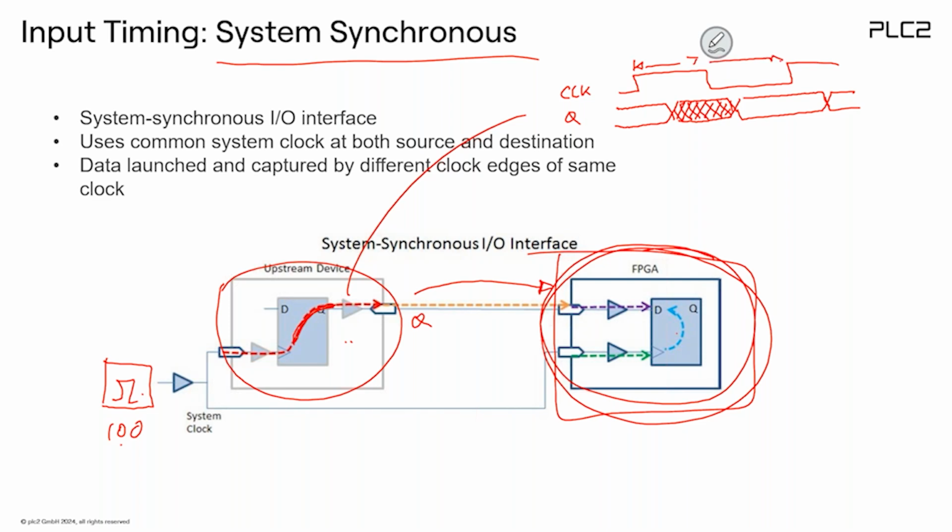Let's say this is from a vendor like Texas Instruments, some component, some chip. In the data sheet you see this information: after the rising edge, for the time T1 min, the data are still the old data. Then after T1 min, the new data appears, and it is stable after the time T1 max. This could be, I don't know, 2 nanoseconds, and this could be 4 nanoseconds. You get this information from the data sheet of this device, you basically put it in, and that's it. That's actually all there is in this section.